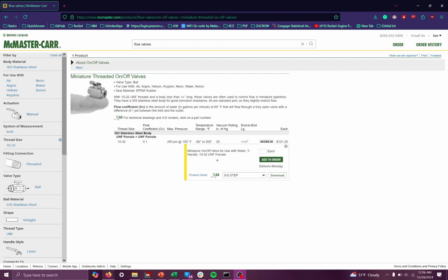And the first step is going to be clicking on the part info tab, and then downloading the step file. You can download a bunch of different file types. Step will make the process the easiest. A few of these are drawings and two-dimensional. These are the 3D models, and pretty much we always just use step. So yeah, download the step file.